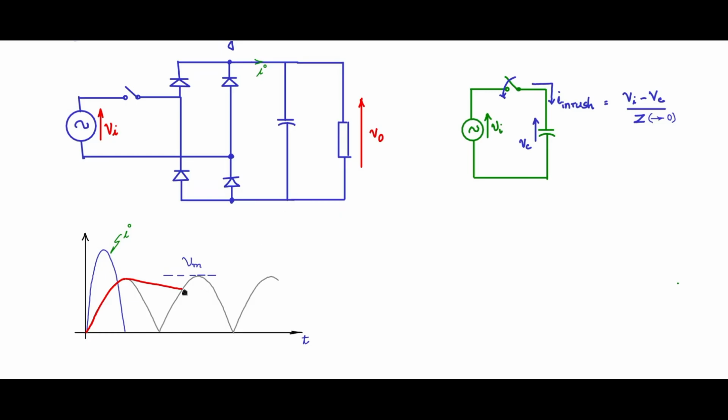And then again when Vi crosses and forward biases the diode, you will see that it charges, the voltage follows the input wave shape, and this repeats. So here actually you have reached steady state. Here there will be a current flow as we have seen in the previous modules. This will correspond to the charge state of the capacitance. So you will see that this peak amplitude is correspondingly smaller compared to the starting peak.